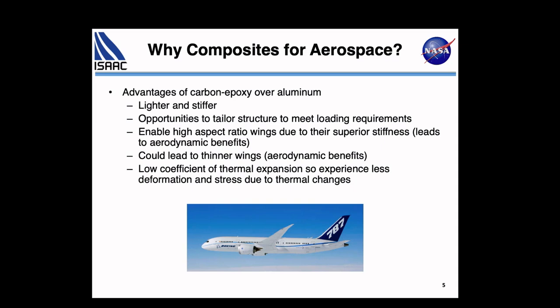The other advantage to going to carbon epoxy is the low coefficient of thermal expansion. That's less important in aircraft for the most part than it is for spacecraft or space structures, which are going to be sitting around either in orbit or on the lunar or Martian surface.